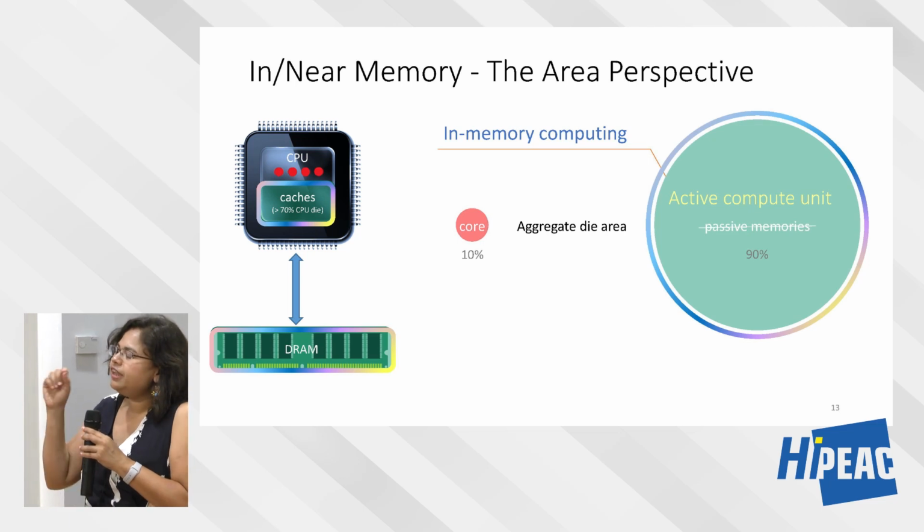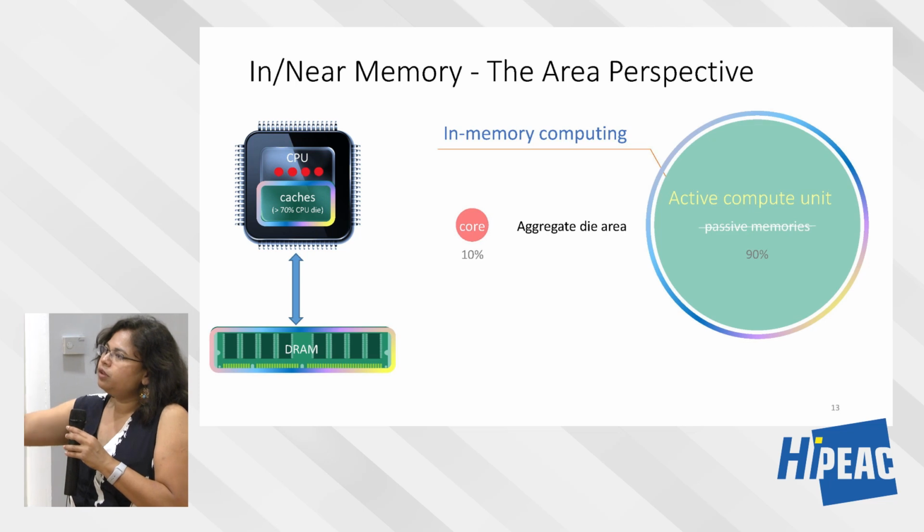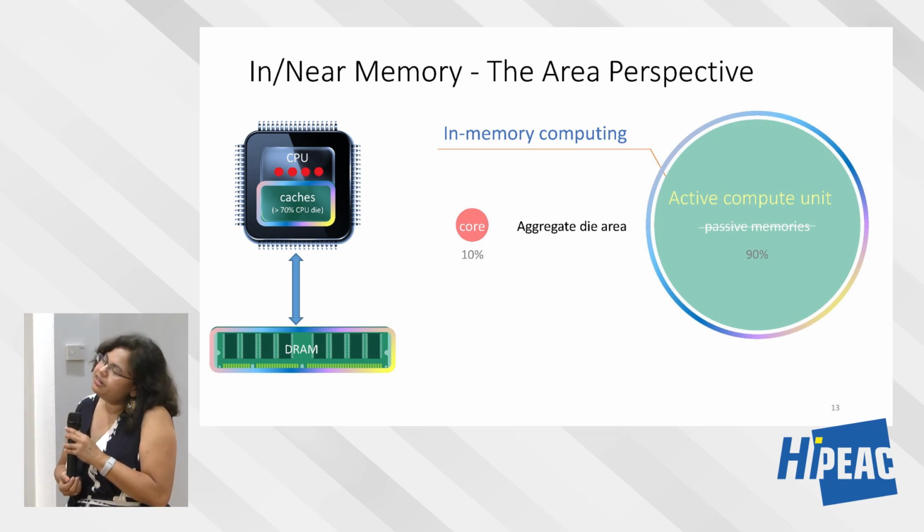Even with SRAM, you still have to do memory accesses, for in-memory as well, and we'll see how. In fact, unfortunately, in-memory even increases the number of memory accesses, because sometimes you have to do bit serial arithmetic or a majority function, which increases the number of times you have to access memory for that operation, and we'll learn about that.